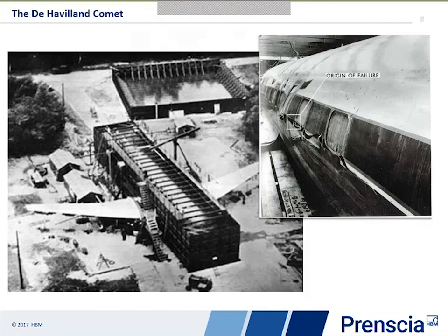In order to investigate this failure, they created a thing called the water torture test. The picture you can see here on the left was at the RAE research facility. They took a fuselage from a real aircraft. This was Yoke Uncle, the third aircraft. It had already done 1,230 real flights.